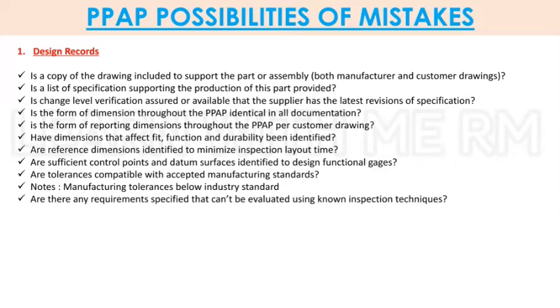Are sufficient control points and datum surfaces identified to design functional gauges? Are tolerances compatible with accepted manufacturing standards? Notes: manufacturing tolerances below industry standard. Are there any requirements specified that can't be evaluated using known inspection techniques?